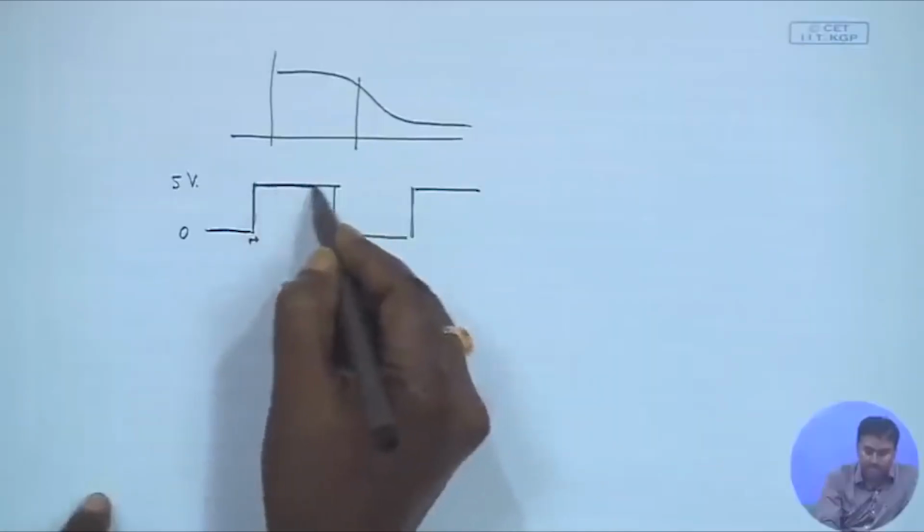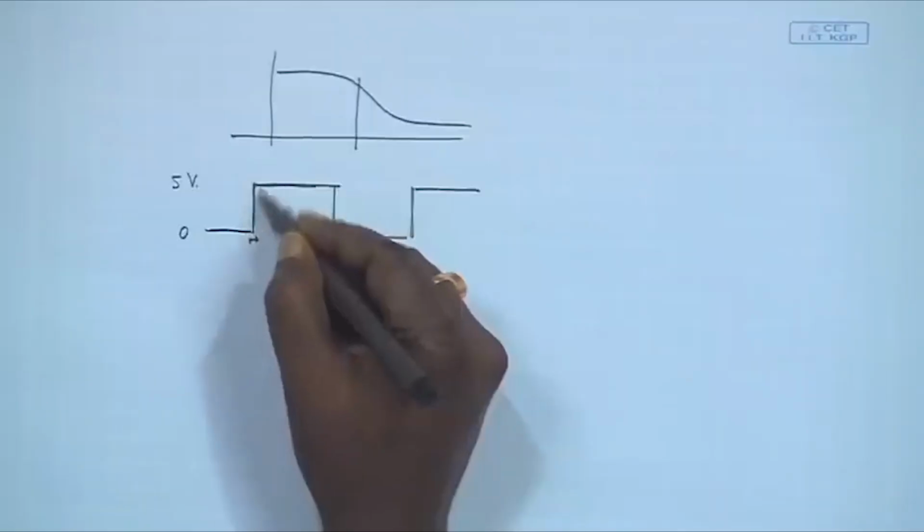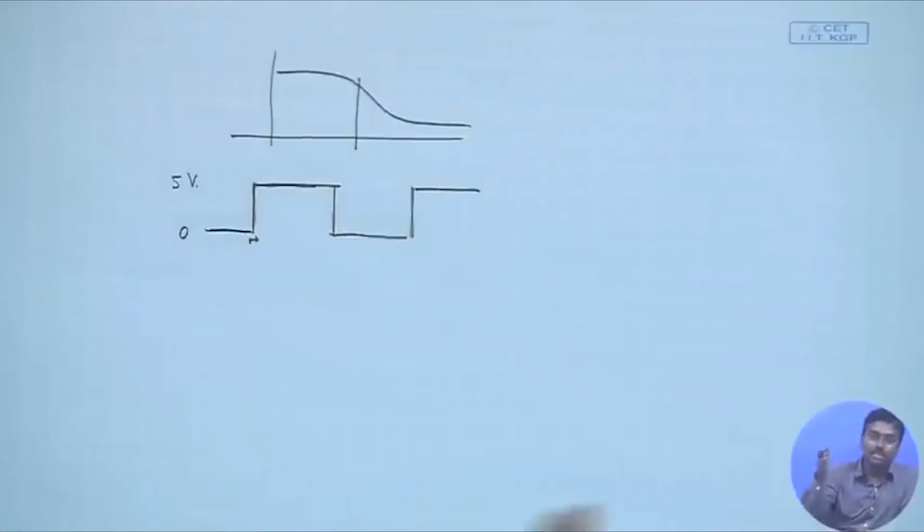This is the part where the signal remains almost constant over time, so probably not many high frequency components are there. So what happens in a low pass filter, those high frequency components will be suppressed. So basically as an effect, this particular part will be smoothened. It cannot really sharply jump because the high frequency components will be suppressed.